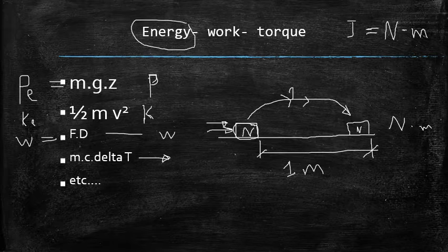Another term is torque, also equal to force times distance, but in this case the torque is the application of force through a lever arm, or it's the force that causes or tends to cause a twisting or rotary movement. So the torque has a fixed lever arm, and we will use a force here at this point equal to 1 Newton. In this example, this is a free end and this is the fixed end. If we act with force in this location, it will rotate the arm.